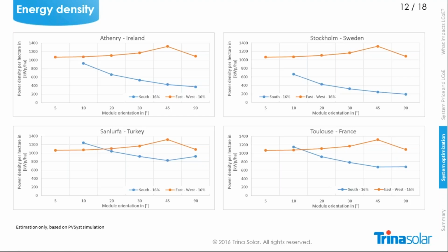This is based on the lowest sun angle. Here in this analysis, I selected the lowest sun height for winter, so I selected the point that during midwinter the system is not shaded during noon.